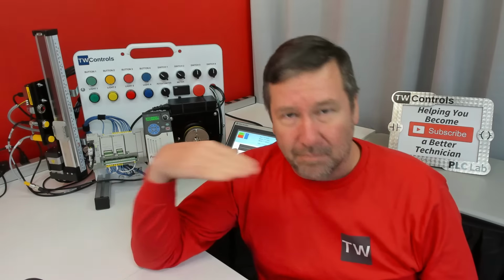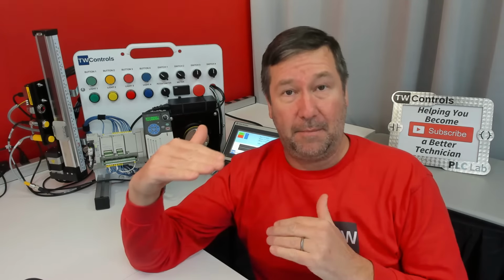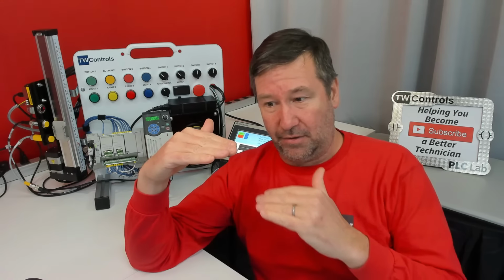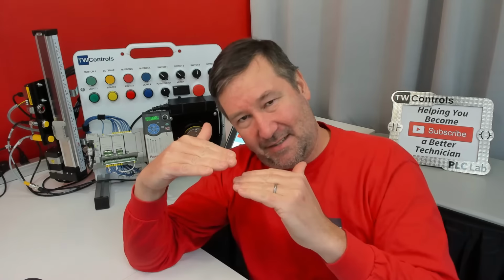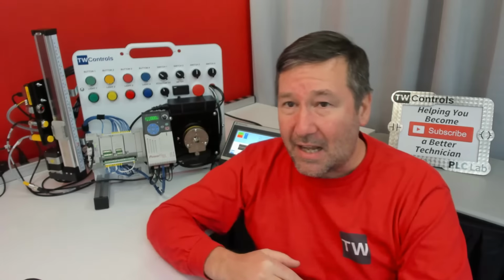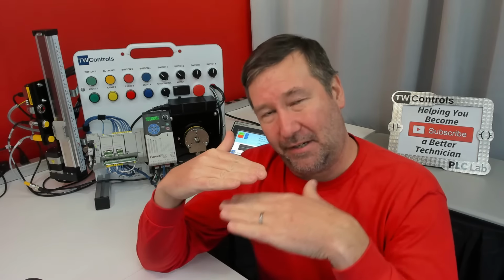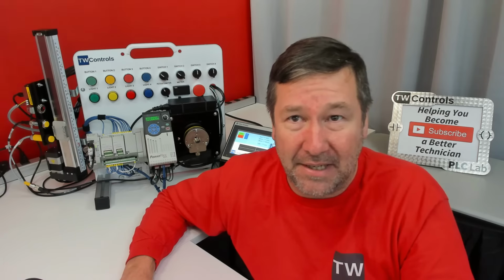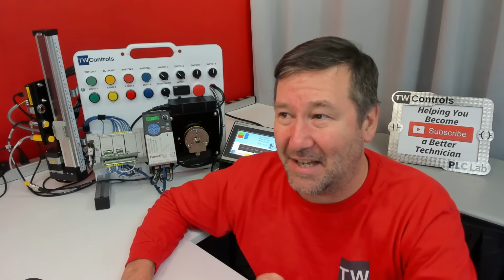So, crudely, what a PID does is it looks at, first of all, how much error there is, and it adjusts accordingly. Its goal, though, is one, not to overshoot. As it approaches the value, it's going to need to do some slowing down. And then we may have some errors where it can't quite get there, so we're going to need to do some corrections over time. The combination of the P, I, and D works all those things out.